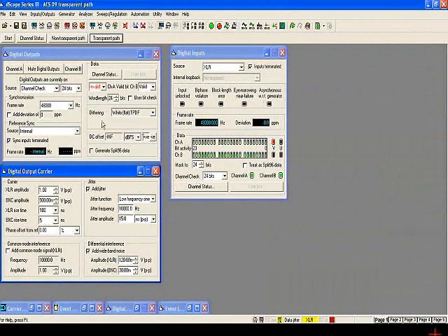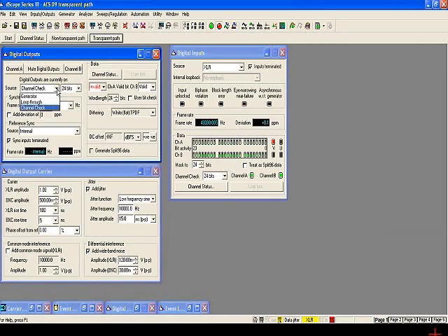Now, the way this is accomplished is rather than have a generator, sinusoid or square wave or whatever we choose when we're in the generator mode, we use something called channel check. And in this case, it's going to be 24 bits. We're going to put it down the path. And then on the other side, we're going to take a look at channel check over here. And we've got 2 green lights. So this is all we need to know. We're putting in a number on one end. The green lights mean we've got the same number coming out the other end.